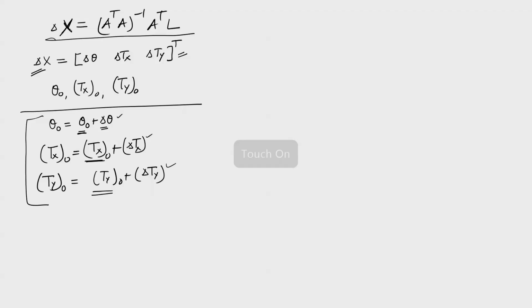So, let us go ahead and see there are some situations where I cannot use the observation equation method. If you remember our triangle example, this angle is alpha, this is beta, this is gamma. Ideally, I can write alpha plus beta plus gamma, which are adjusted values, equal to 180 degrees. So, this is the condition equation.